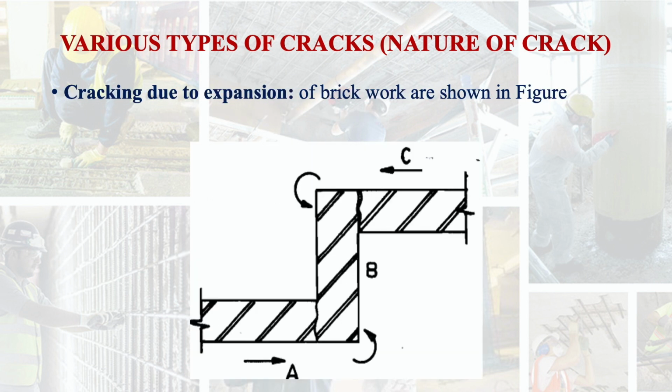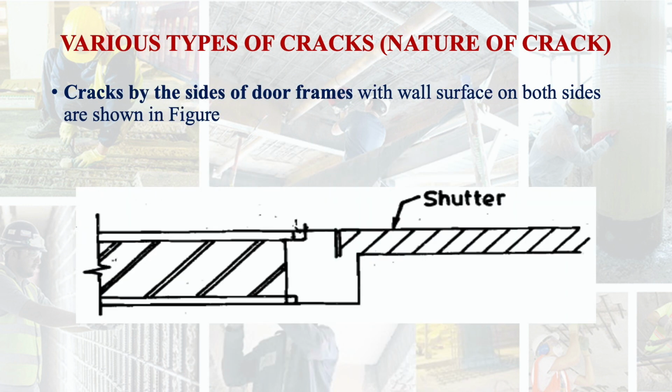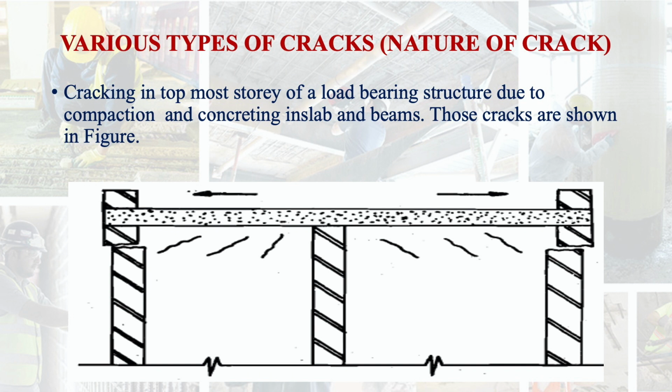Cracking due to expansion. Cracking due to expansion of brickwork is shown here in this figure. That due to the expansion in the different portions, there may be cracks in the wall. Then cracks by the side of door frame with wall surface on both sides is shown here in this figure. Then cracking in topmost story of a load bearing structure due to compaction and concreting in slab and beam.